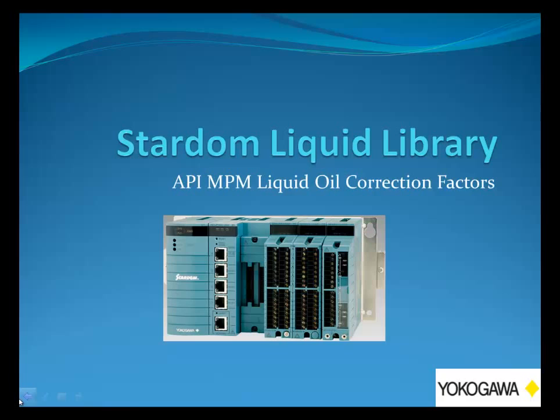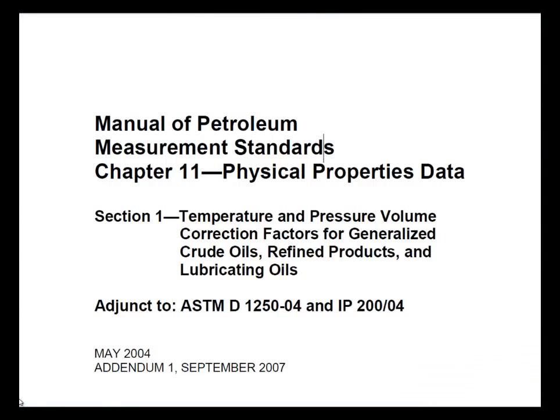Today I'm going to cover Stardom's liquid library that's based on the API MPM liquid oil correction factor standard. Specifically, that's the API MPM Chapter 11.1 standard that covers temperature and pressure volume correction factors for generalized crude oils, refined products, and lubricating oils.